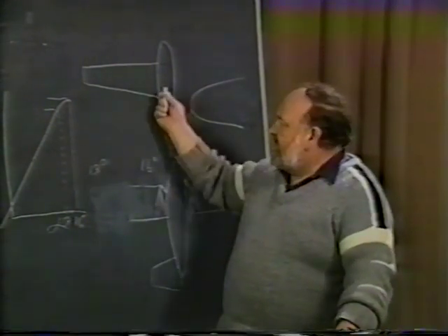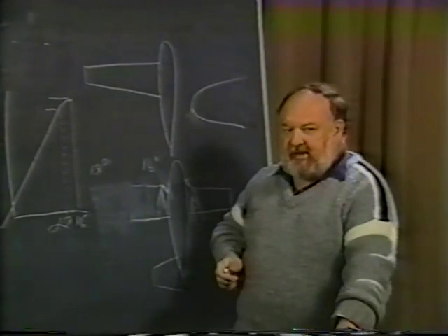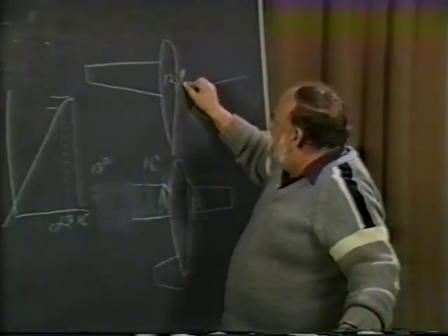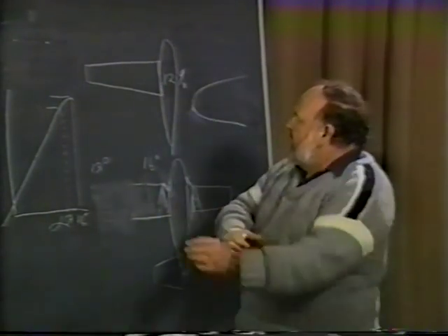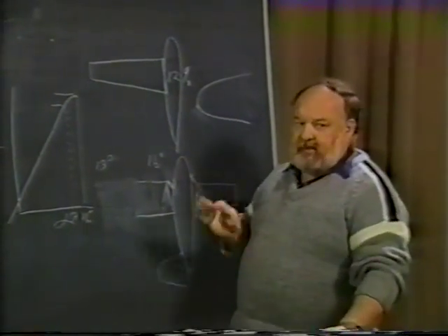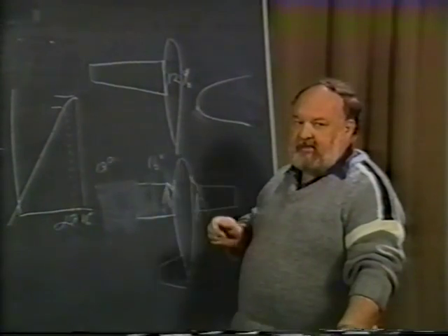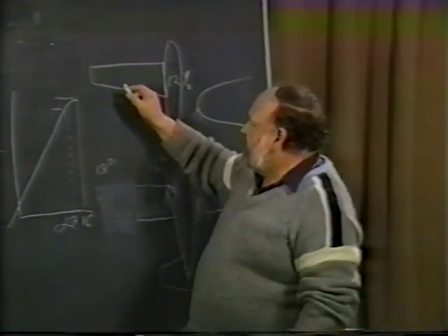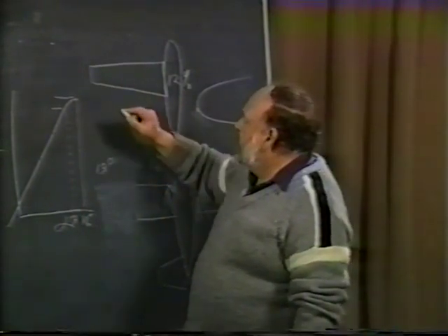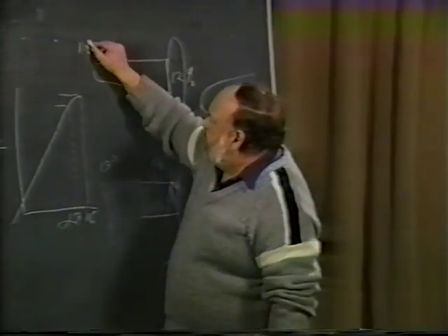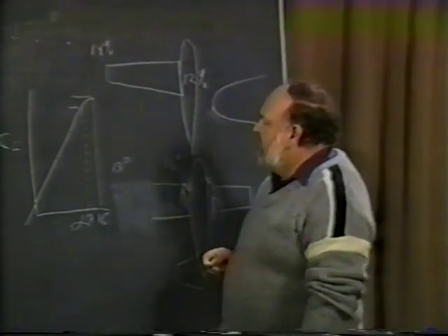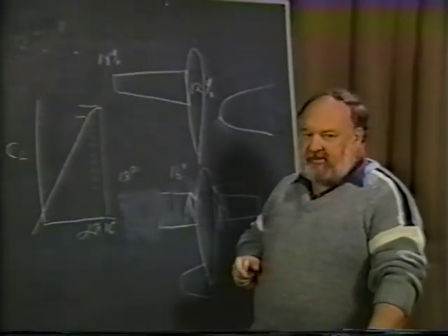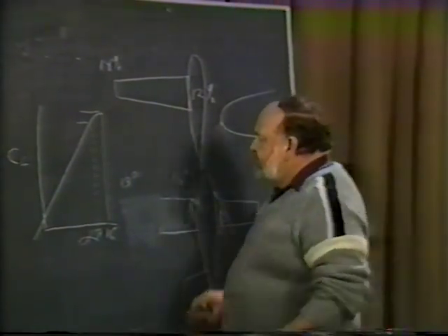Well, one of the things we did, we changed airfoil section in actual thickness. We used a 12% thick airfoil at the root. This was not very thick, but the airplane was a high-speed airplane. We did not need any thicker than that. And we went the opposite way of what the conventional thing to do. Instead of using a thin airfoil at the tip, we went to an 18% thick airfoil at the tip. But the fact that the chord was less, that the wing tapered and the chord was less, from a head-on view,